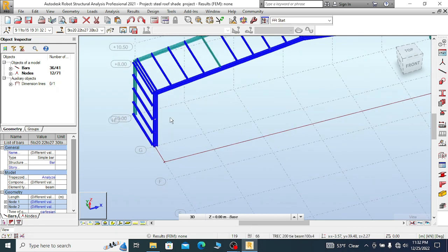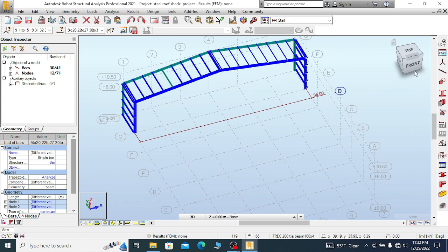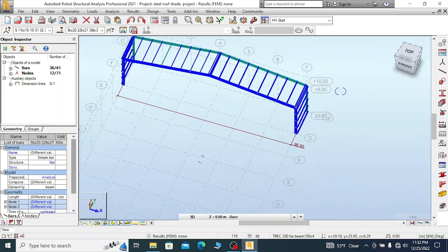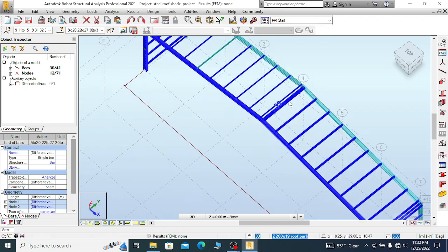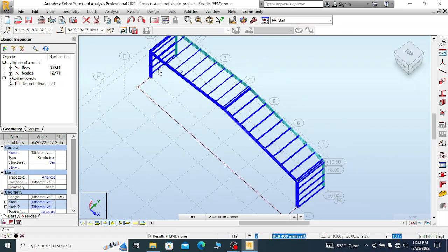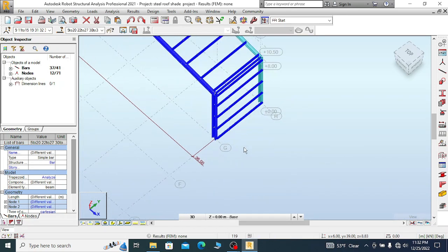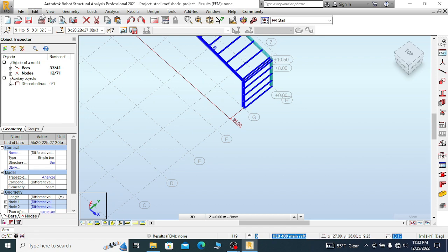All the purlin, all the tie beam, all the columns, and the internal main rafters must be selected. Okay, be sure. Here this member is not selected now. I may select. Okay, now let me replicate this selected element to the right of the axis.